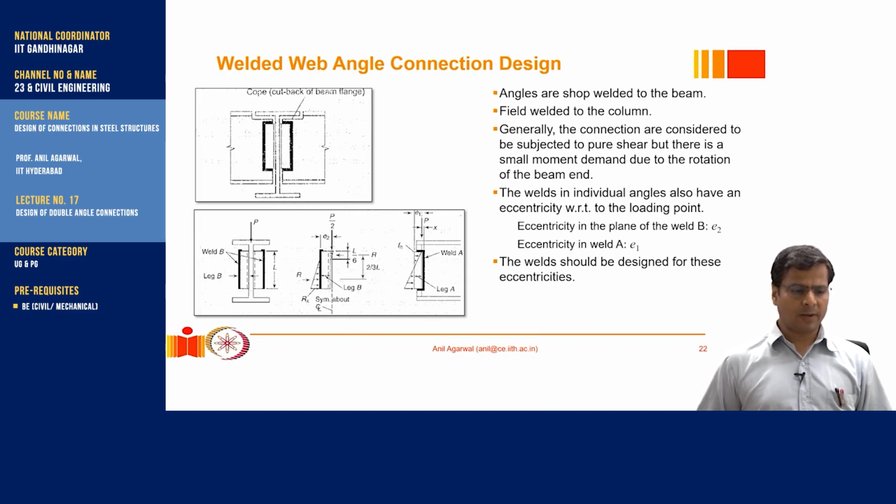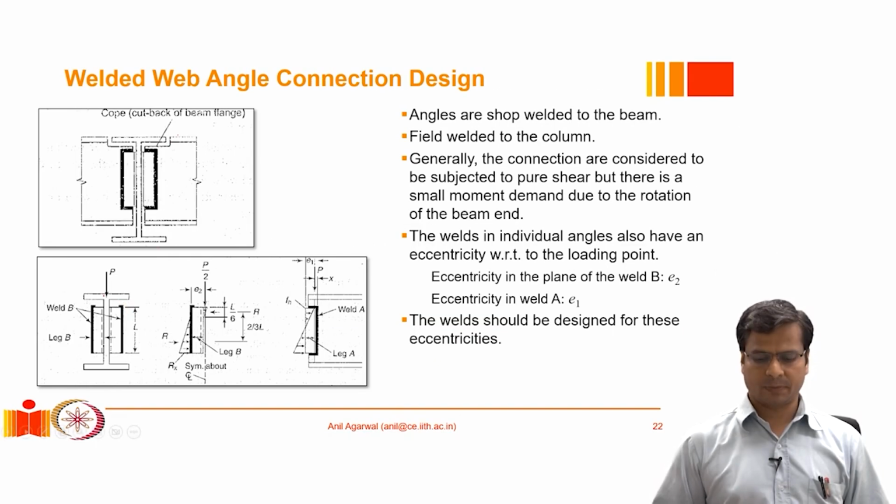Okay. Here also you might notice that in such situations we should always provide a return weld at the top. We have discussed this topic when we were talking about the dimensional restrictions on and the termination of a weld. We had talked about this, that the return weld is essential near the top of this kind of a weld.